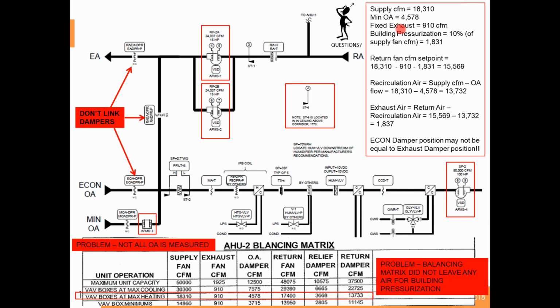However, if you go through this example, we only need a certain amount of recirc air coming down this duct, of 732. We need to exhaust some air. We need to relieve some air. And my caution here is, if this is closed, but yet this needs to be cracked open and it's all a single output, you're going to run into trouble.